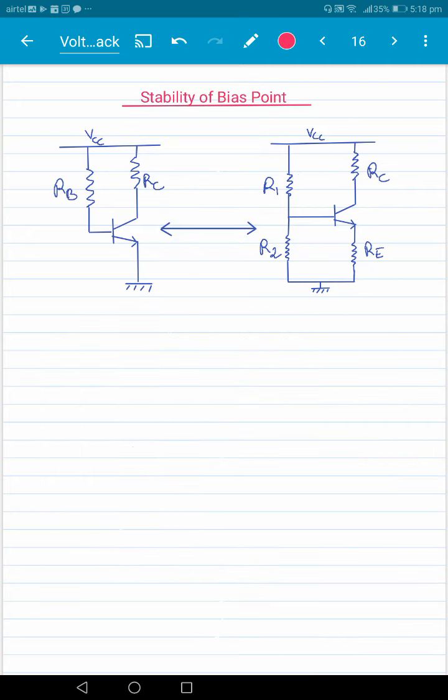So to summarize, what is being said is that when you compare two circuits and whenever you gain something, so here circuit number 2, the voltage divider bias. Yes, in voltage divider bias we get beta insensitivity, right? That is obvious, and every book talks about it, that circuit achieves beta insensitivity.